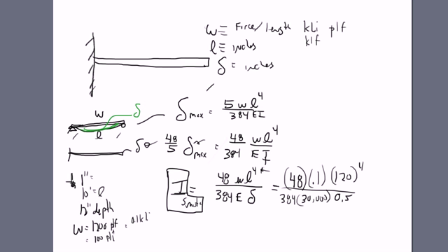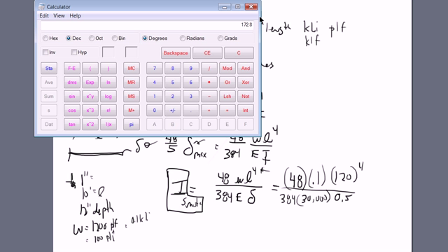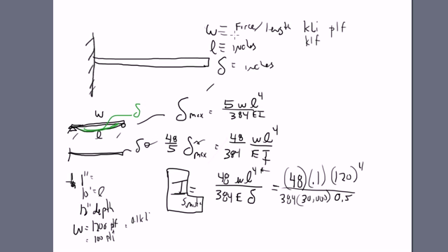I'm sorry, I keep on saying that. 1728, let's see what that is. Again, 172, I'm sorry. So we're going to tell you that the required I equals 172. Remember, that would be inches to the 4th power. And if we're going with a 12-inch deep beam, then the section modulus required would be that divided by 12.